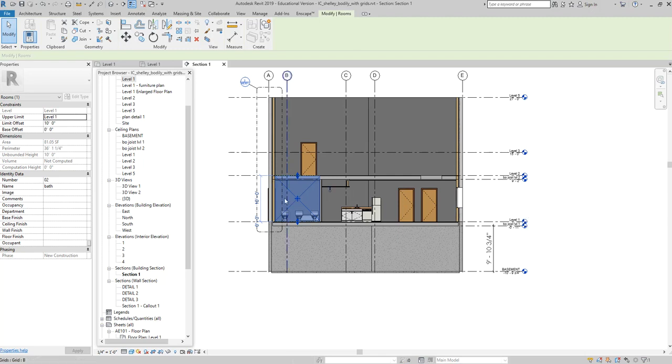All right. And you're like, yeah, big deal. What does that mean? Well, when you get really advanced in Revit, you can assign things to rooms like occupancy, or engineers use it for calculations, how much air volume needs to go into a room, right? Occupancy types, room finishes. There are like 50,000 different things you can assign to a room, right? And the intent behind that will be to schedule those items, all right?